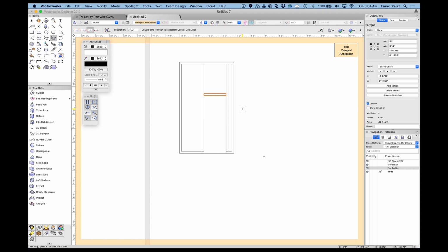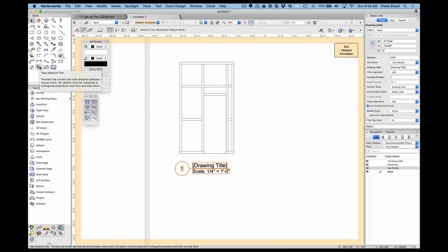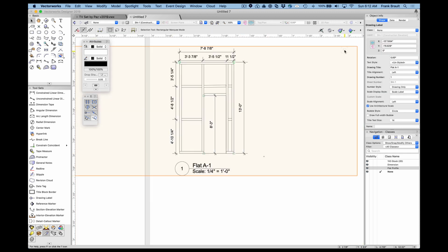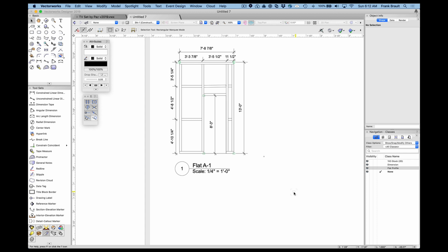Our polygon tool is configured to trace in the outline of the flats with framing. Our trim tool is used to control where the butts of the rails and stiles are created. Another couple of strokes create the toggles, and the whole flat is optionally ready for extruding into dimensional framing.